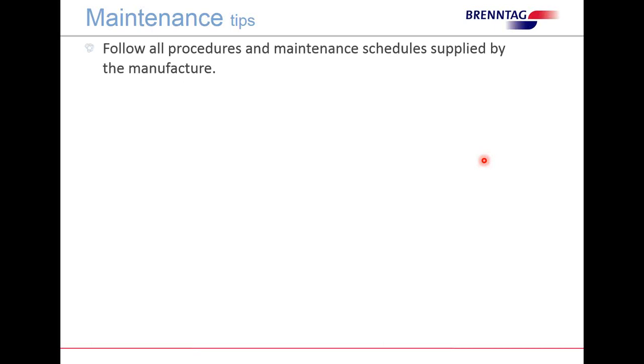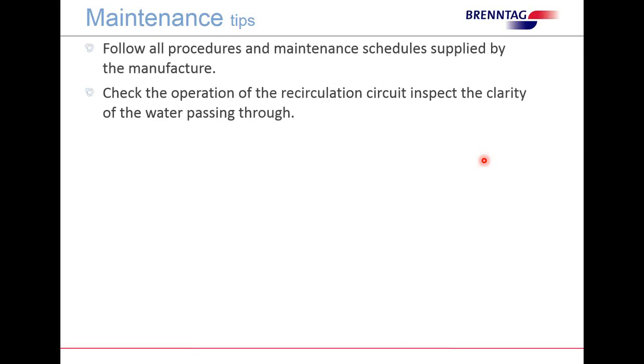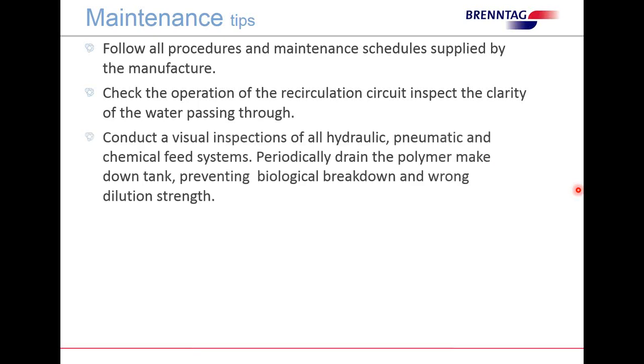You always want to follow the procedures and the maintenance schedules supplied by the manufacturer. Check the operation of the recycle circuit, inspecting the clarity of the water passing through it. Make sure the water is not dirty in your recycle. You want to make sure you have good, clean, treated water coming back through on your recycle in a recycled DAF unit. Conduct visual inspections of all hydraulic, pneumatic, and chemical feed systems.